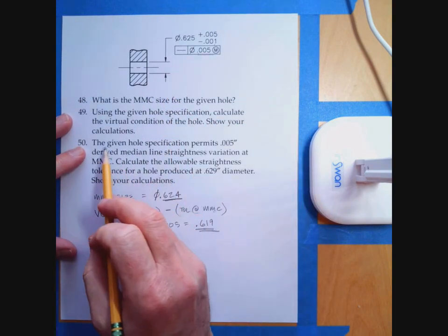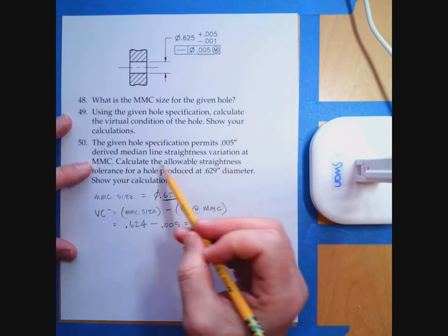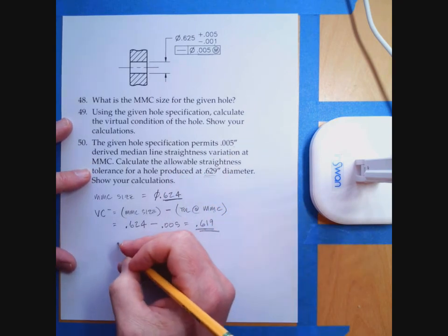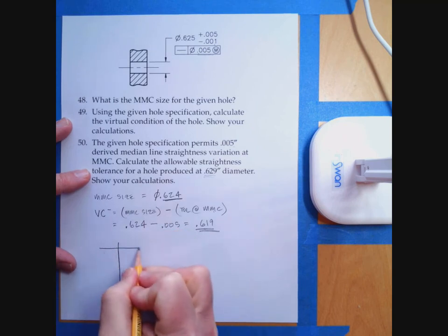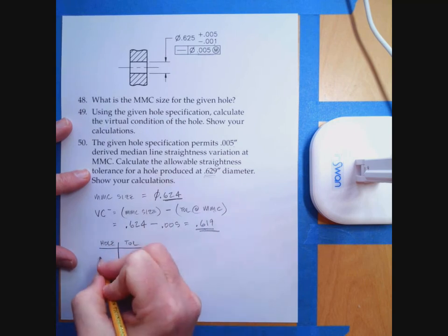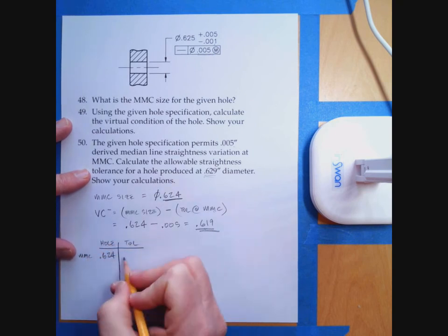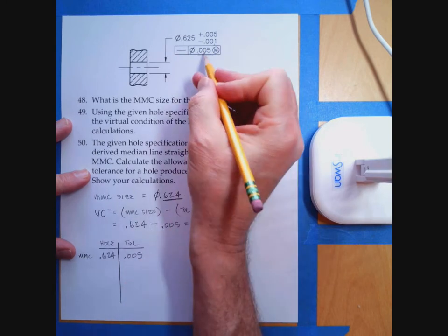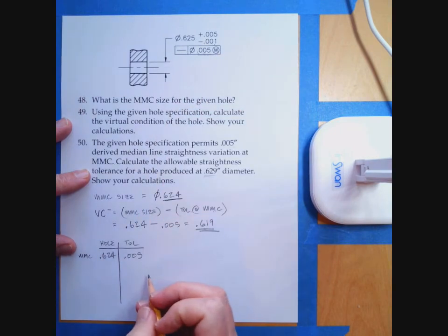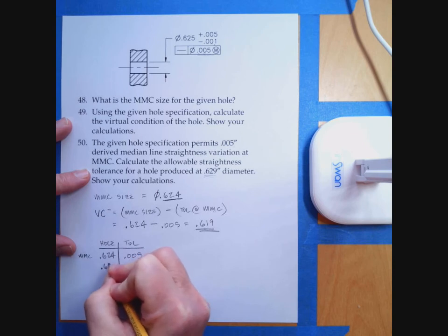And then finally, the given hole specification permits 5 thou derived median line straightness at MMC. Calculate the allowable straightness at 629. So again, like I always do, I like making this little chart. So we'll make the chart and we'll do the hole size here and we'll do the tolerance. And at 624, which is the MMC size, the tolerance is 0.005, right? 624 is the MMC size, and 5 thou is the tolerance at MMC. As we deviate from MMC, it's going to go up. It's going to go 625,